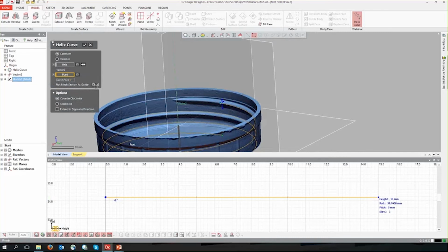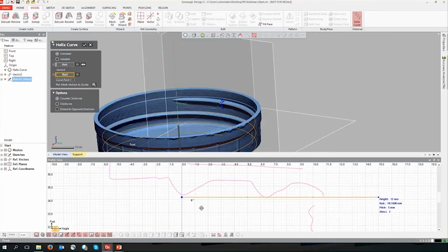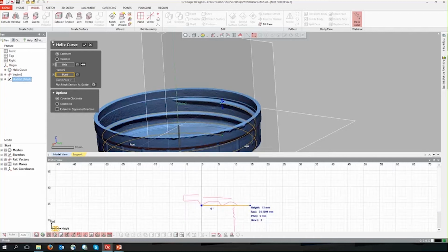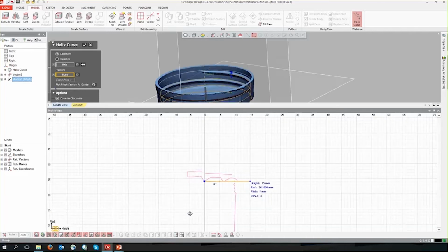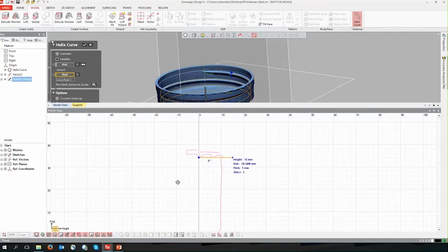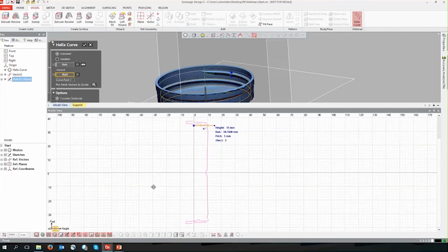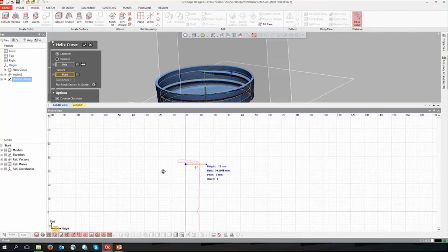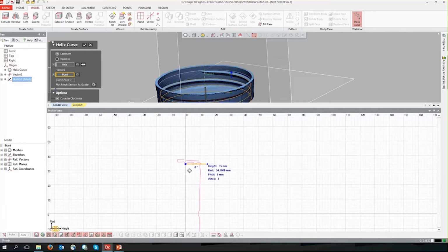So there is also this plot mesh section as a guide curve. So this is very handy for if we have screws that have a different radius, right? So we start off large and we go smaller, or we go smaller and we go larger, so like a funnel sort of thing. The bottom is going to represent this information. So if you're familiar with the variable fillet, this is the same sort of dialogue, as well as the 2D mesh sketch, right? So we have this preview of a cross-section of our mesh with this reference polyline, which we can start constructing our helix from as a guide.